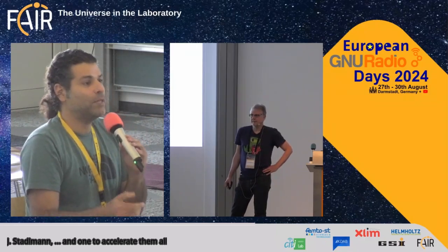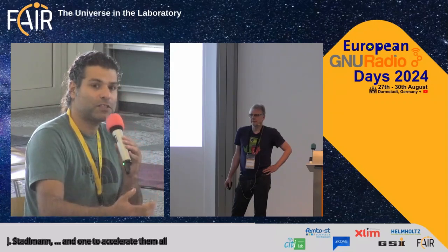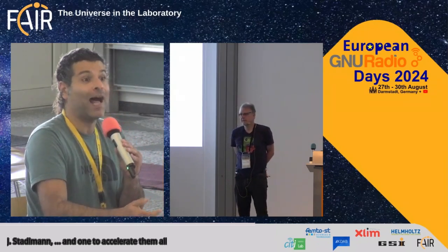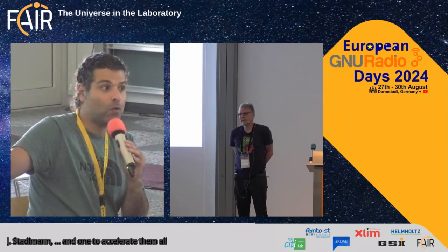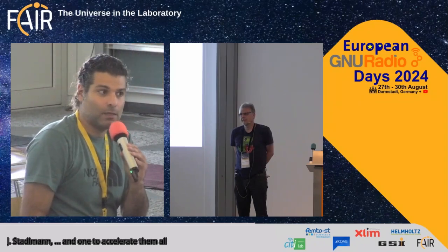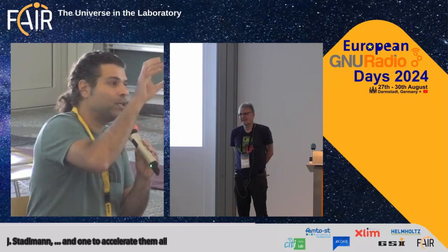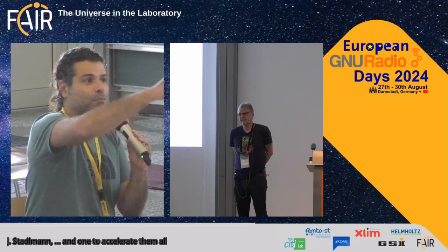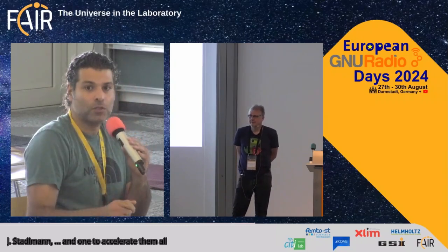And this is where finally GNU Radio comes in, because we need very versatile data processing, online and offline. While we are recording everything to disk and sending it over to the great green cube over there for data processing, at the same time we have an online eye: just by putting a graph over there, we take a branch and make a Fourier transform and, for example, a conditional signal on it.